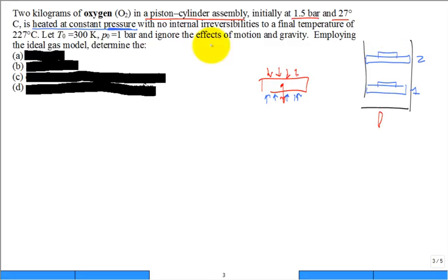All right. There are no internal irreversibilities. Right away, what does that mean? There's no internal irreversibilities. No entropy production or exergy destruction. One way you can say that would be sigma equal to 0, because it's a closed system. You're going to be doing a process from initial state 1 to 2. If you want to put a subscript 1, 2 on there, that's fine. Or you could put that exergy destruction 1 to 2 is 0, also 0.